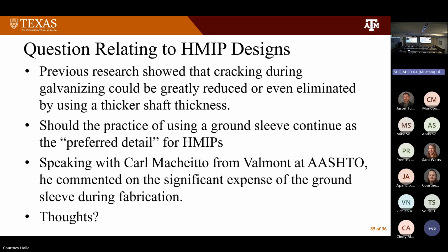So, but the handhold cracking, I'm not that worried about. David sent me some pictures of someone that had some vertical cracks. It looks more like a hydrogen embrittlement type problem that was probably there from the start, but again, it's just growing. I wouldn't be that worried about it up at the handle unless it's ridiculously large and growing. If it happened a few feet up from it, and it's not all around the base, it's a very localized region. So I personally would not be that worried about that, but